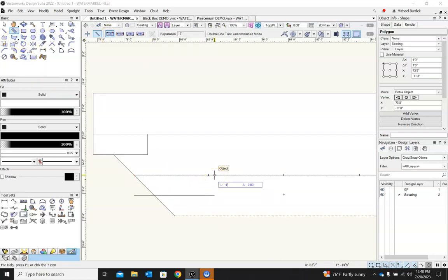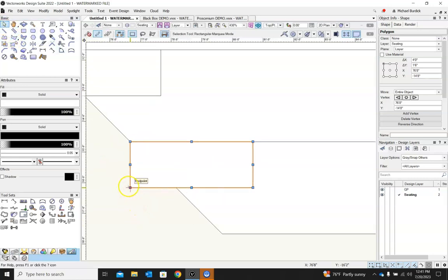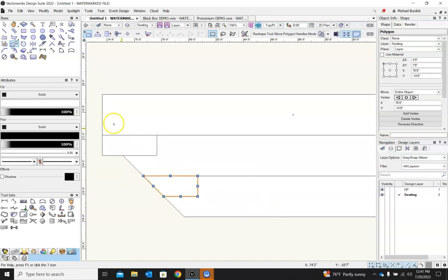Here that comes across at 4 foot. And there's another one here that comes across at 4 foot. So again, I'll manipulate these a couple different ways just so you can see. Double click the corner to bring up your reshape. Oop, that one's good.